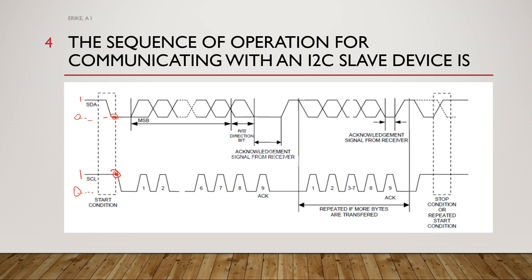In other words, he receives an acknowledgement bit from the one it writes to, and then it sends to the one that wrote to it. All right. Okay. So the master now will terminate the data transfer by pulling the SDA line and the clock line to a high position, both of them.